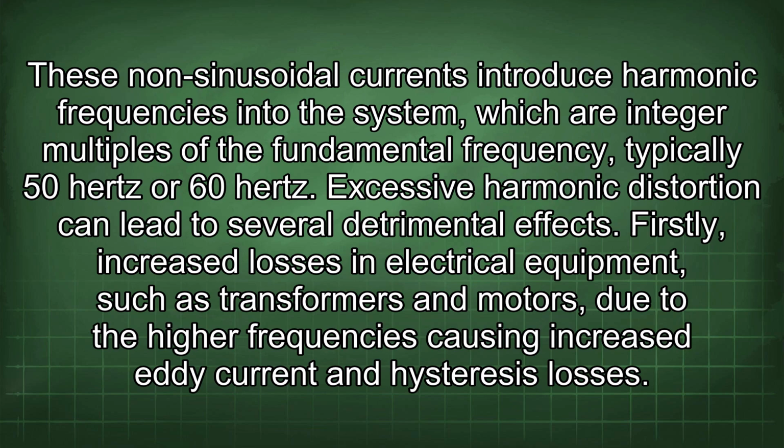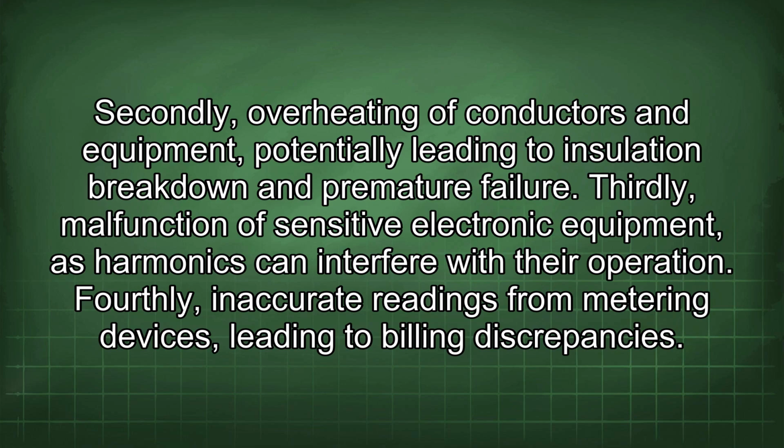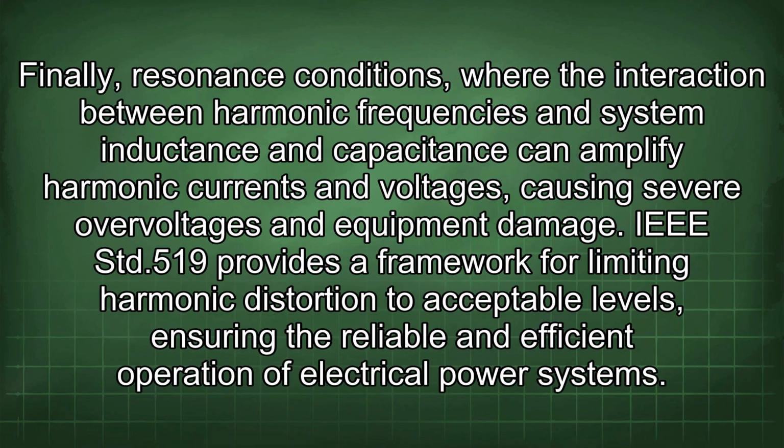Firstly, increased losses in electrical equipment such as transformers and motors, due to the high frequencies causing increased eddy current and hysteresis losses. Secondly, overheating of conductors and equipment, potentially leading to insulation breakdown and premature failure. Thirdly, malfunction of sensitive electronic equipment, as harmonics can interfere with their operation. Fourthly, inaccurate readings from metering devices, leading to billing discrepancies. Finally, resonance conditions, where the interaction between harmonic frequencies and system inductance and capacitance can amplify harmonic currents and voltages, causing severe overvoltages and equipment damage.